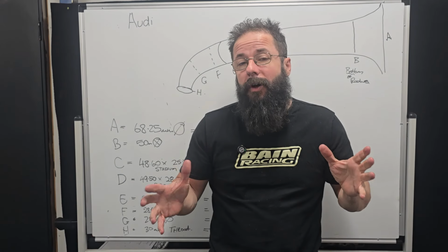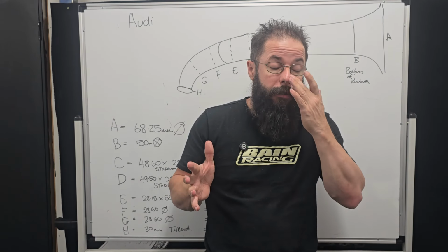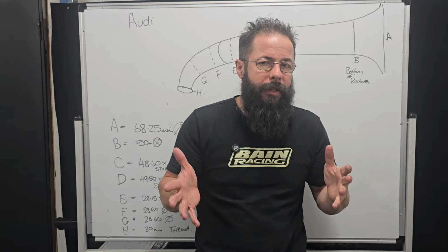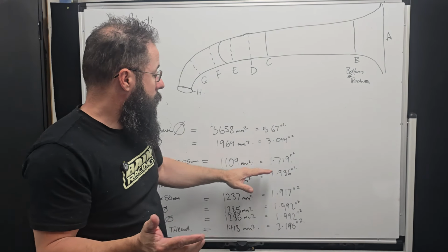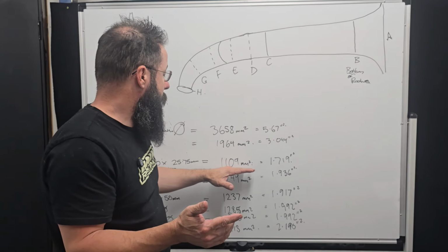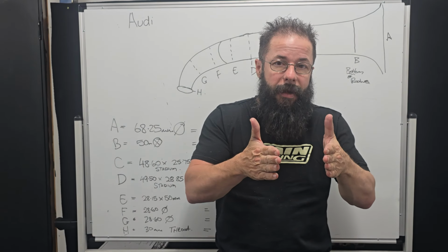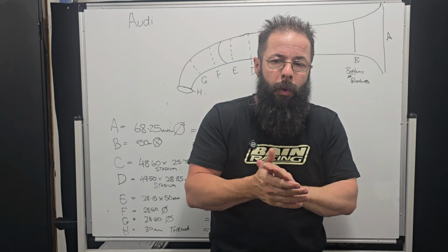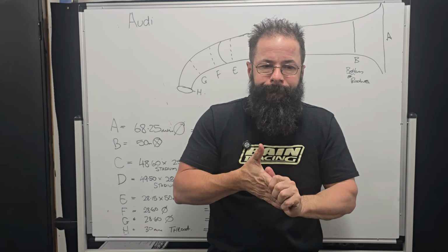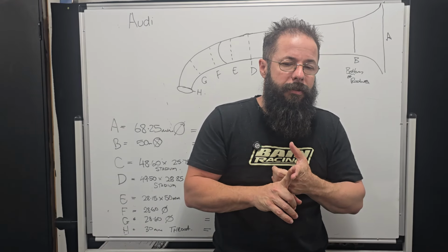All right, guys, so we've got our sizes and we can see some problems straight away. The manifold actually has a tight spot in it right about here. That was our 1100 square millimeters. So it actually tapers down in the manifold, then pinches up to, or comes back up to the manifold window. So from here, we really need to work out what our minimal cross-sectional area is.